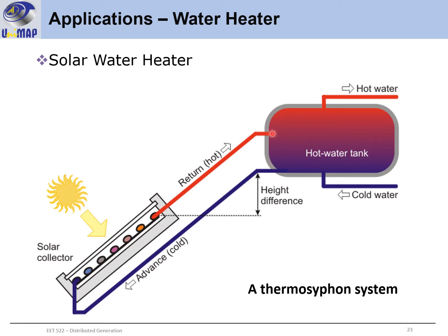Okay, and the tube will heat the water in the hot water tank, and the cooler water, after it has the heat exchange in this, the cooler water will go down again, and it will be heated up again within the solar collector. Okay, so the requirement for this system is the collector must be installed below the storage tank so that the warm water will rise into the tank.